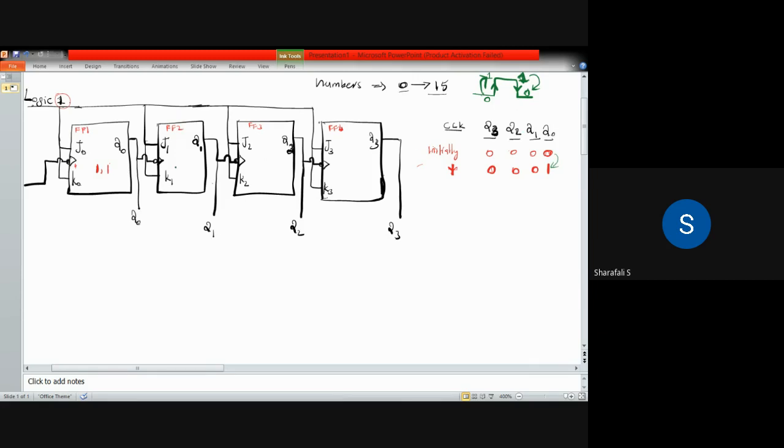I'm talking about the case of the second flip flop. For the second flip flop, the pulse is at the positive edge when Q0 is changing from 0 to 1. So Q1 will not change, because the second flip flop is at the positive edge, but we need the negative edge of the clock pulse in order to have the toggling effect. So Q1 will be retaining its state.